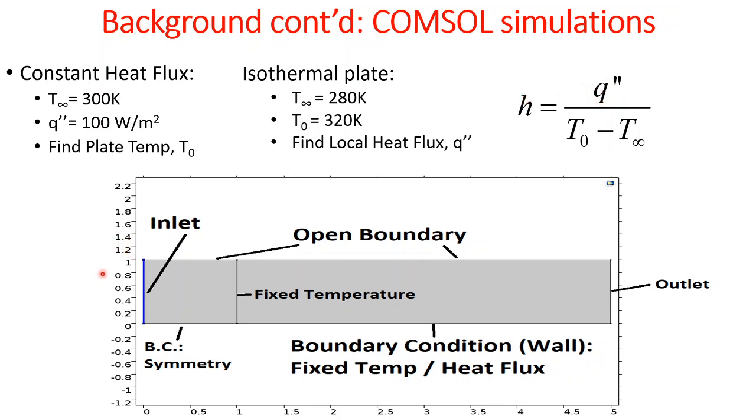So just to go over the simulation that I set up here, here's the graphics of it. This is largely identical to the simulation that Dr. Ramos showed us earlier on this semester in COMSOL. Just to remind you, on the leftmost side here I have the gas inlet, and for this first chamber here, the bottom has a boundary condition of symmetry, and the top of both chambers have an open boundary such that they're not chambers at all, and so it doesn't model confined flow. This is a free flow.